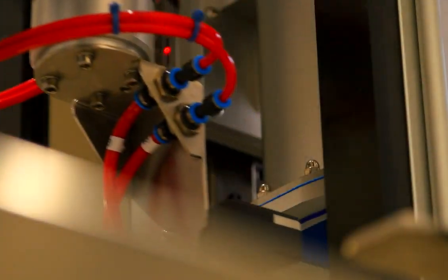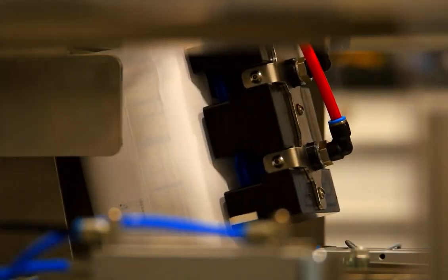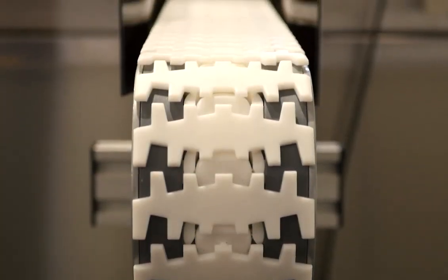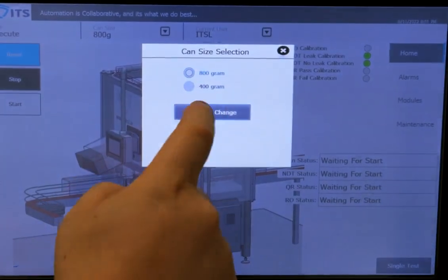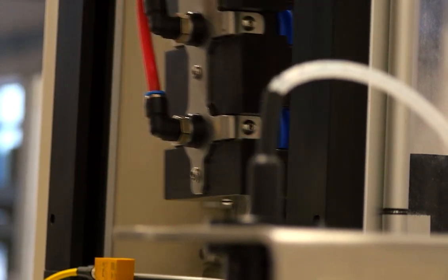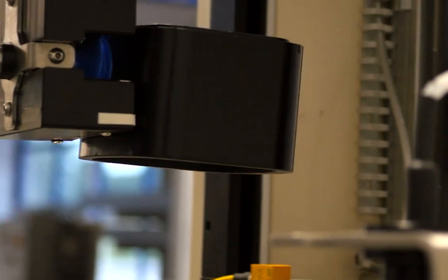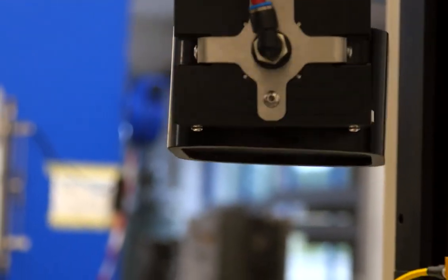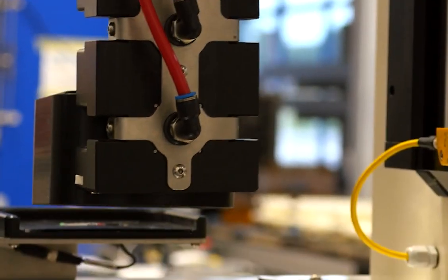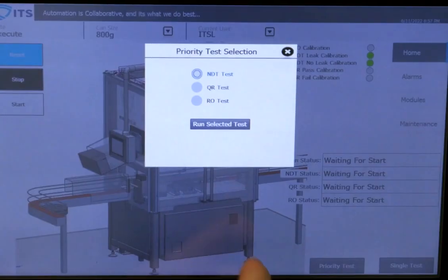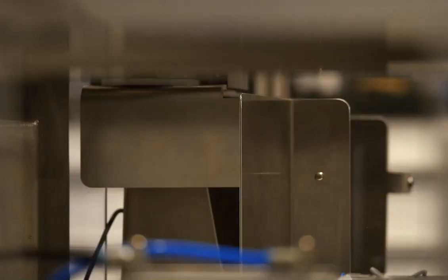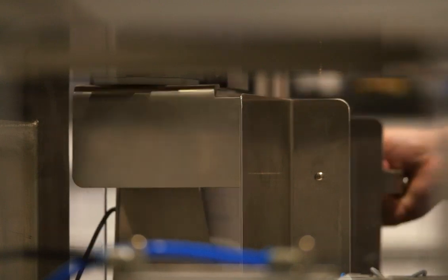This week's application focus is from Cobots.ie in Cork in Ireland. Our partners have created a complete automated testing cell. At the heart of the cell there is a UR5E robot, which is inverted. It has a custom gripper that can pick up the product, present it to a camera so it reads the barcode. It can then present the same part to a different scanner to read a data matrix on the top seal of the part. These two codes have to consolidate together.